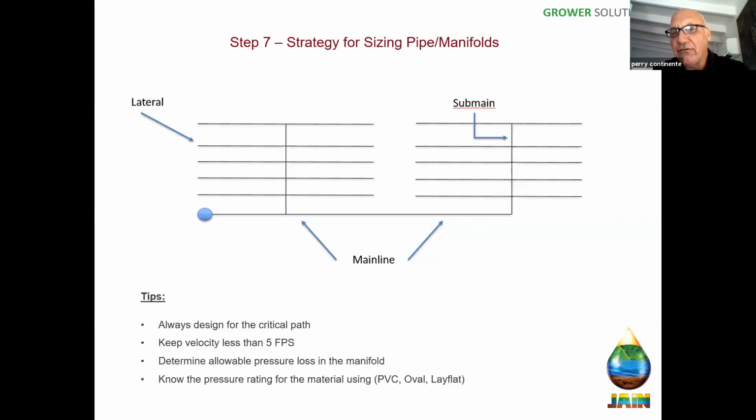Some acids go downstream because if you're injecting a strong acid, they can't go through the filters. If you're injecting an acid as a water treatment, well, then it can go upstream of the filters. And there are a few products that are not meant to go through a filter. That being said, I still strongly advocate putting the injection upstream of filters. So another one of those, it's not a deal breaker. You're going to listen to your customer, but if it was up to you, it'd be upstream of the filter.